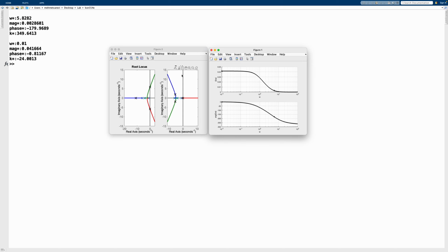Not zero, but a little bit more than zero. And we will not have 100% overshoot, we will have lower overshoot. Let's assume 95%. If we move a little bit more, it will decrease k a little bit more, and then the zeta value will be increased a little bit more. Therefore, our overshoot will drop a little bit.